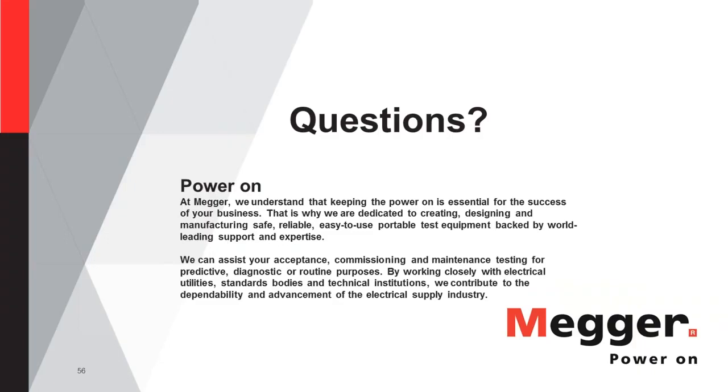I have a question here that says the skin effect due to doubling of the frequency causes heating in the rotor. Can we say doubling of frequency causes increased hysteresis and eddy currents, which vary with the same power of frequency? That's true. That's absolutely a different way of understanding the concept. There are so many ways you can deduce the heating effect. This is the right way of understanding the concept. That's true.